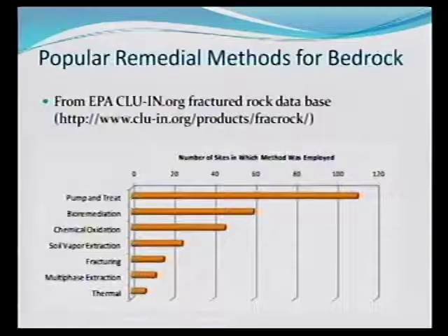All right, so these are the methods: pump and treat, bioremediation. So this is both, I think, natural and stimulated. Chemical oxidation, vapor extraction, fracturing, multi-phase extraction, meaning they're pulling out free product. And then finally, thermal. And in many cases, multiple technologies were used.